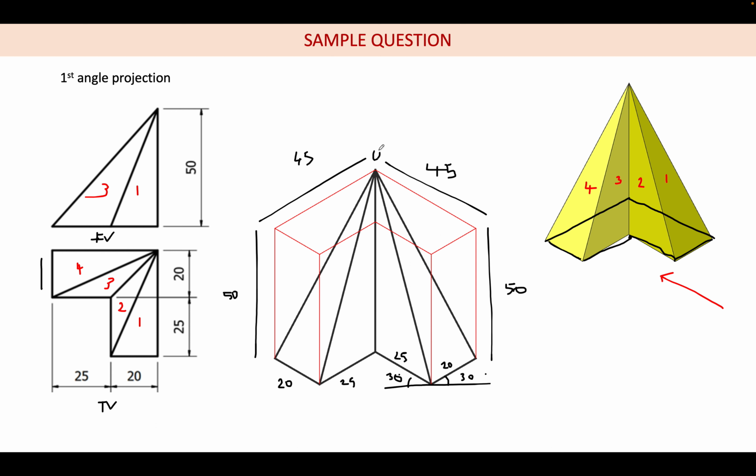So let us say this is point O. So I am going to connect all these lines. After that you can see that this is the isometric view. So finally this thick object with the black color is the isometric. This L-shaped object I drew for reference because it will be easy. We cannot directly draw these lines. After drawing this L-shaped object only, we are able to know from where we are going to connect it. So like this we are drawing it.